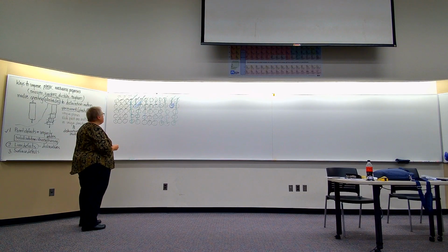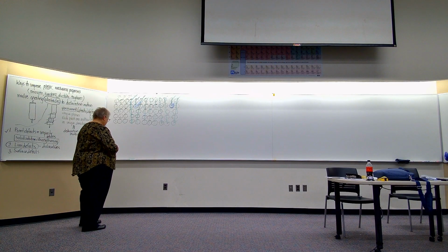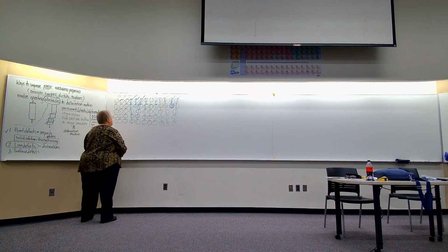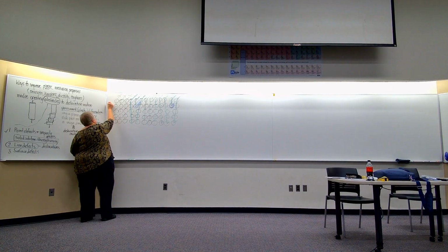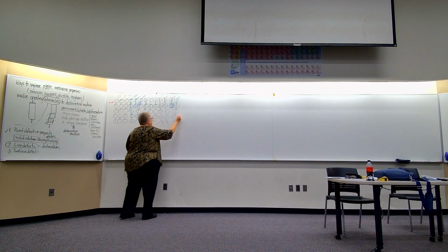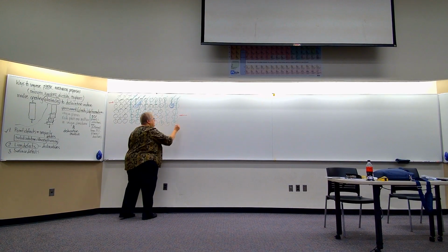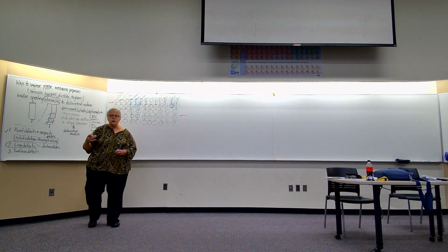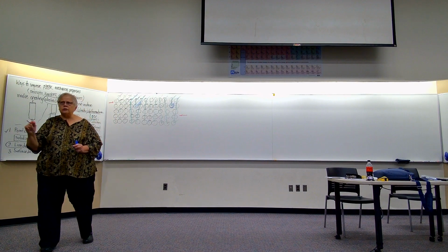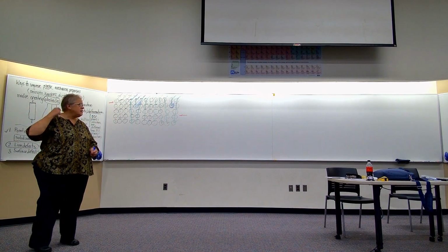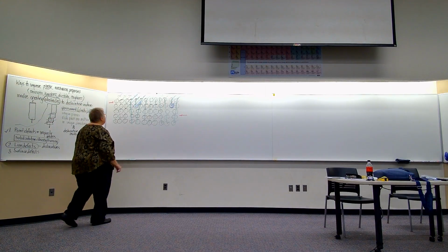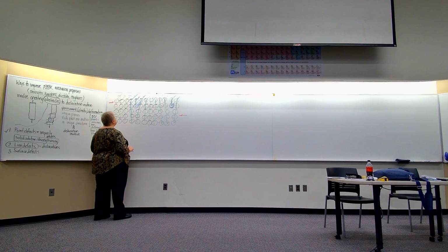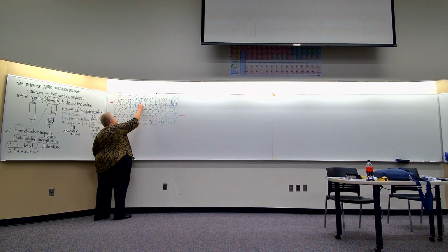See that? All right, so let's say I apply a shear stress. And by the way, permanent deformation happens because of the shear component of an applied stress. So I'm applying some shear stress, and once that stress gets big enough, this bond breaks.